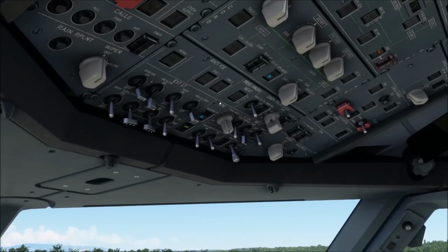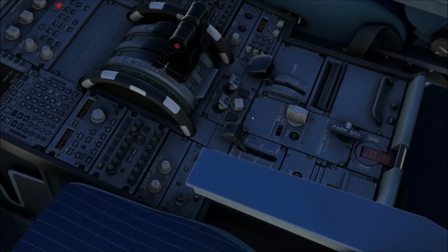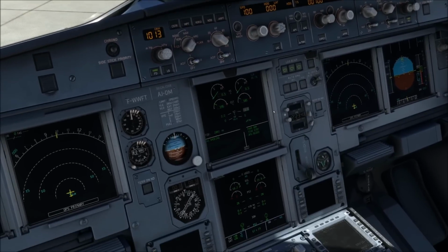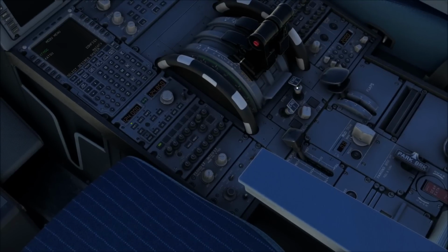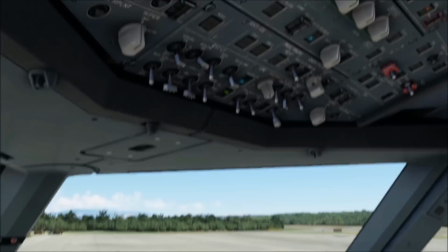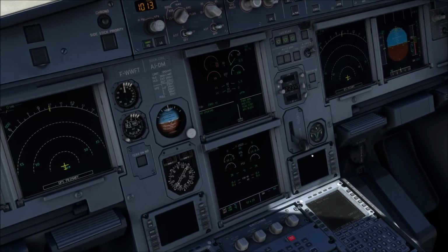We've got the APU, we've got APU bleed, so all we gotta do is flick that beacon light on, put the engine into ignition start, flick on the engine start switch, and voila, it is starting up. Now that is the very easy way, and that is the way that you're all familiar with. So let's quickly reverse these and make things a little bit more interesting.